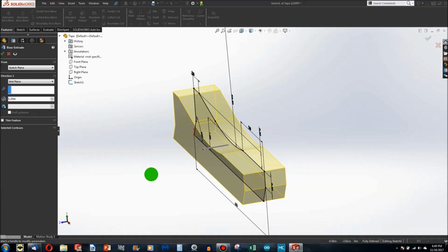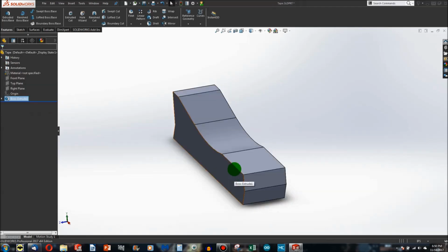That is a very, very good one to use. I wish SolidWorks would default to the mid-plane, because when you go to add a feature on one side, you can mirror it across this plane to the other side, which we'll be going over later on. So mid-plane is probably the best way to make an extrusion, in my humble opinion. You can also go up to vertex, up to surface, offset from surface, and up to body, which I will be covering shortly. So when I extrude this mid-plane, boom, there we go.